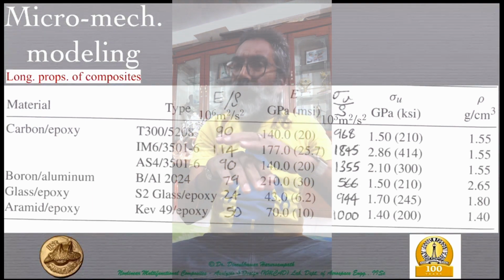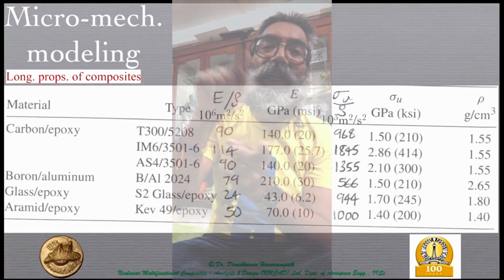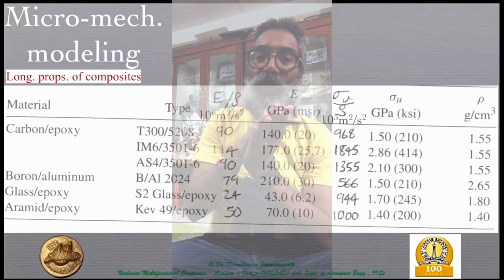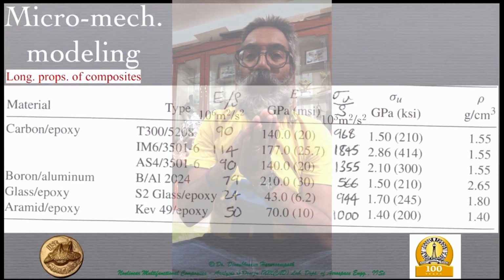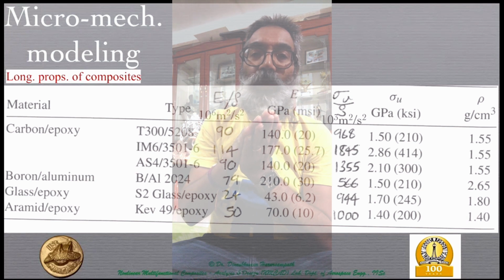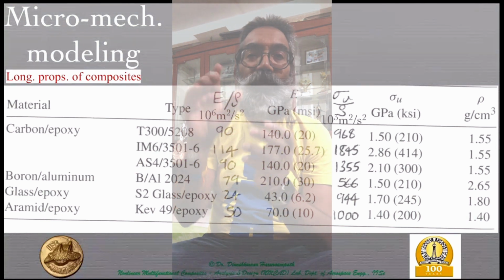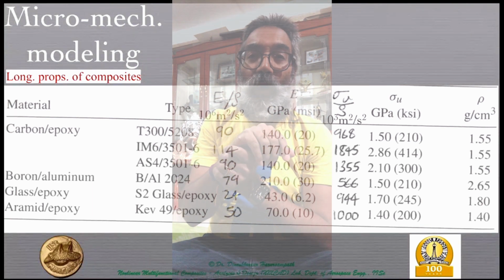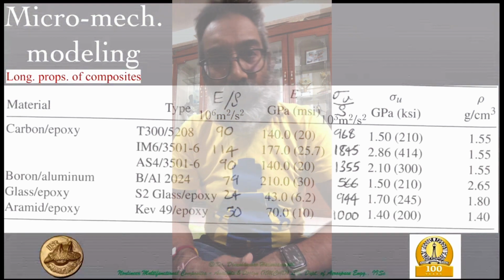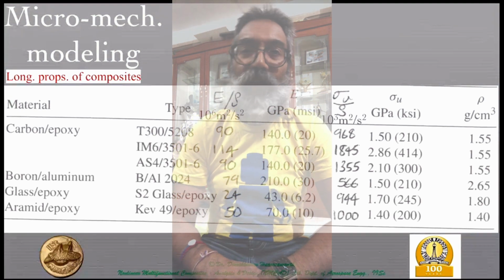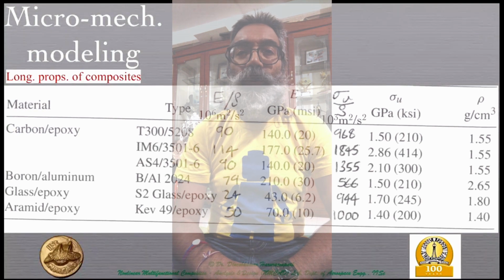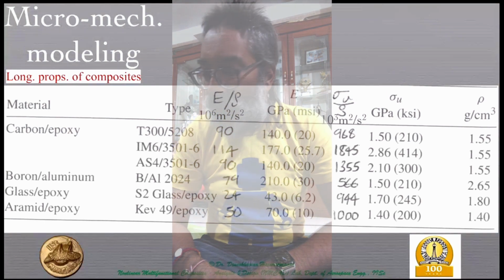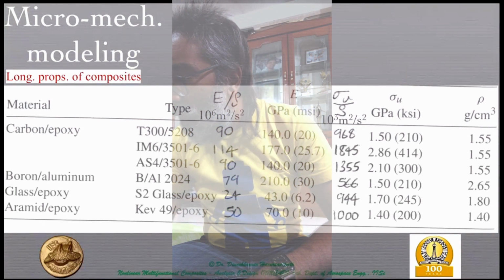Yes, the upper wing skin also undergoes a little bit of fatigue, but the range in the variations of the stresses is not as much as for the bottom, which is the reason why fatigue is even more important at the bottom, tensile loading, rather than on the top, which goes into the compressive regime as well. And therefore, even with a slightly smaller fatigue life, it would be okay to use the 7075-T6 over there compared to the 2024. So that is an important thing.